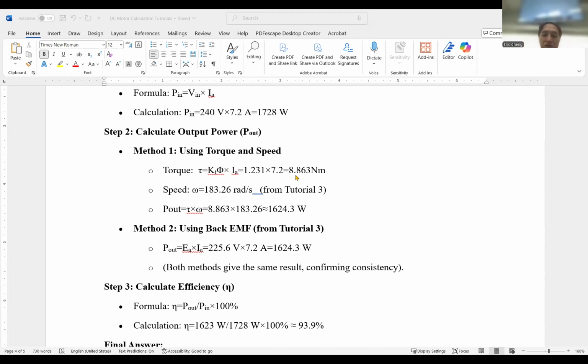So that's what happens when we start up from standstill: because we have no back EMF, the total 200 volt, although it's a 40% duty ratio, will be applied to the resistor and it gives you the maximum current. You can see this from the armature standstill circuitry. Because internally you have an inductor, this current will be held there.